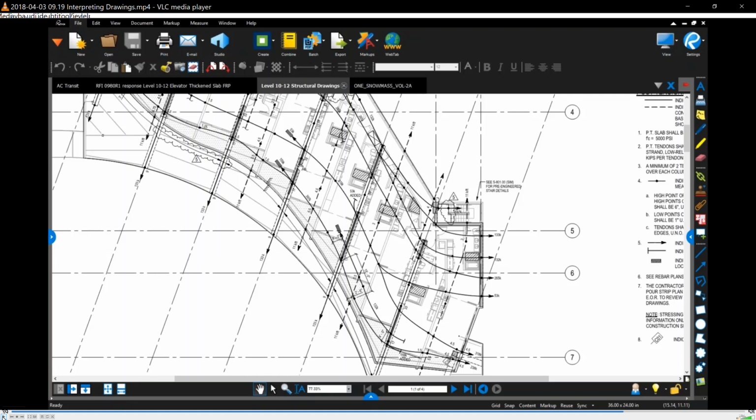Nice. Yes. I have a question. Why do they show 2 different types, like different units? Yeah. So one's for the uniform cables that are spread out equally. So they give the amount of force average per foot. And so then, like Griff was talking about, the PT supplier will then do the math to figure out how many cables they need at what spacing to equal that force. Whereas the dark hard lines on this one are total kip, so that's a banded group. So you put an equal number of cables in that zone over the columns to act like your beam.